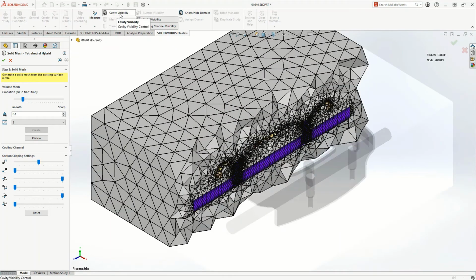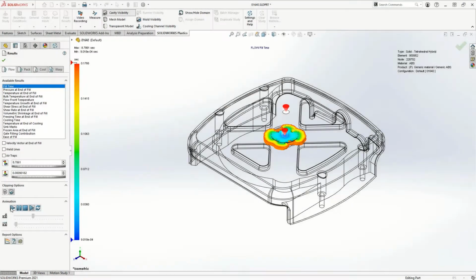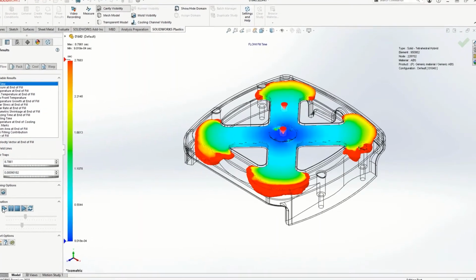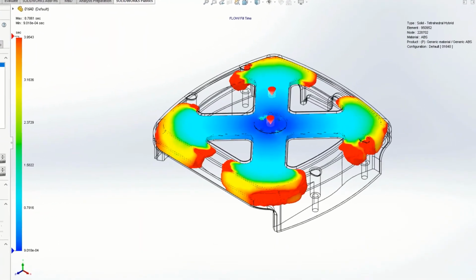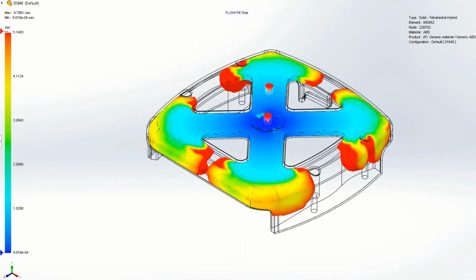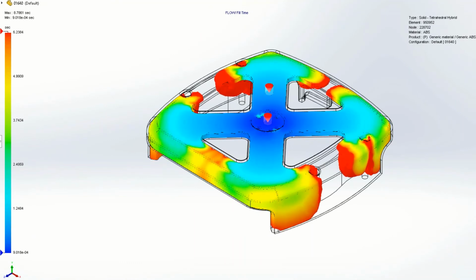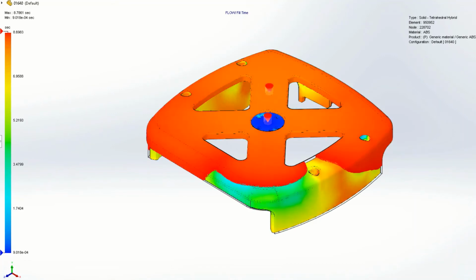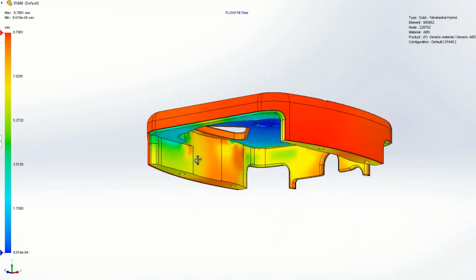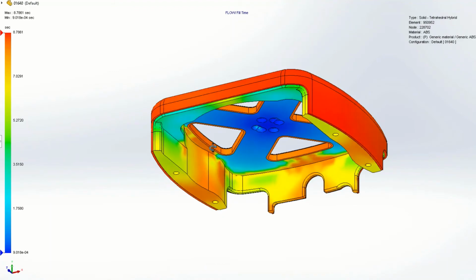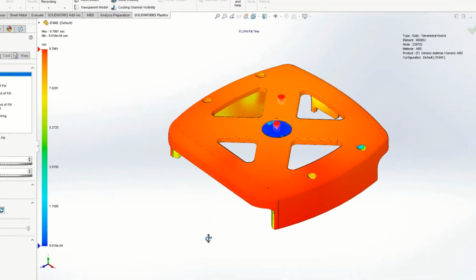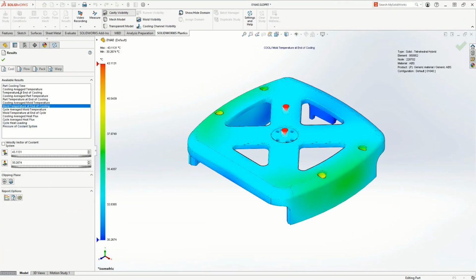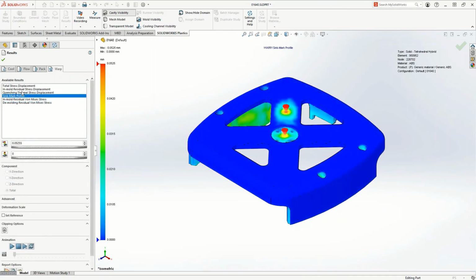They are now fully meshed and modeled appropriately, giving you more accurate simulation cooling results without the need to fully model the cooling channels and the physical components that make up those special inserts. By defining the entire simulation study on the 3D model in virtual domains, it has enabled a more dynamic workflow where you can look at and evaluate different scenarios in your design before any of the heavy lifting is done. The results themselves, which include the new multi-material overmold injection process, are now more accurate when considering cooling, giving you confidence in your injection molding process before you even start designing or investing time and money into the mold itself.